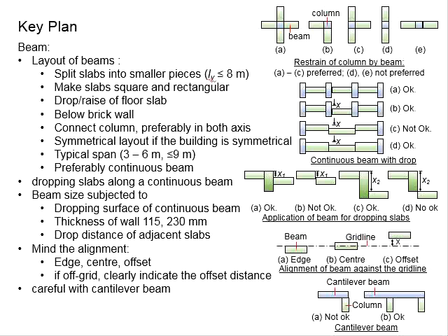You know that the loading by nature, especially when we are talking about the imposed load, is something which is movable. It can be there, it can be not there. You cannot guarantee it's always there. Therefore, you must avoid the cantilever beam on both sides being supported by something at the middle. There will be a problem with the structural integrity.